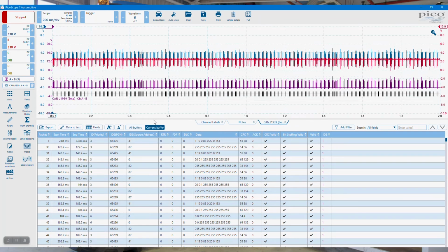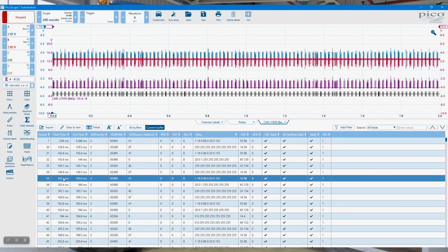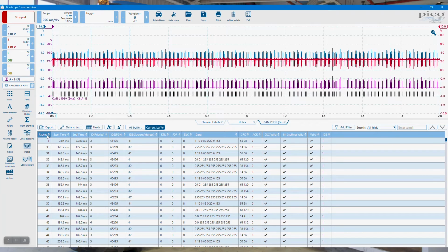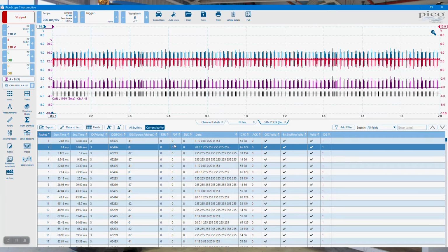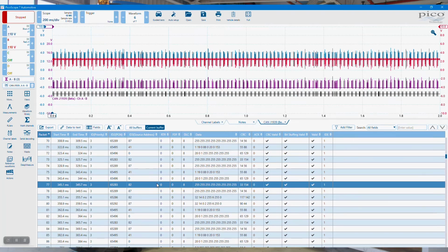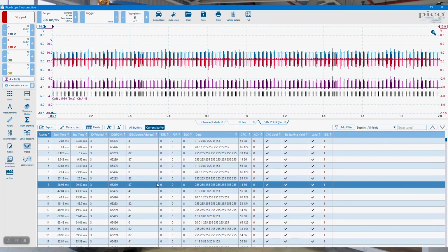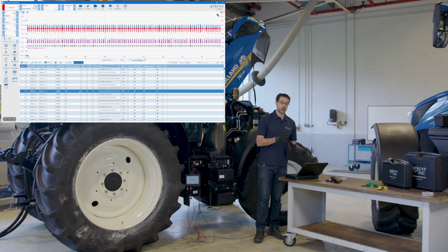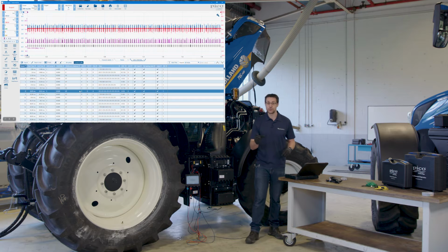Now, as we can see in our table, one thing to be aware of is the order that it goes into. If it's not in numerical order, just click the packet number and that will automatically put it into a list that is more reflective of what was going on. One of the key differences is how we've set this decoder up in this guided test: we put the format into decimal. Now, decimal is a different way of viewing it. Typically, it's usually hexadecimal, but you can usually find parameter group numbers listed in a decimal value.